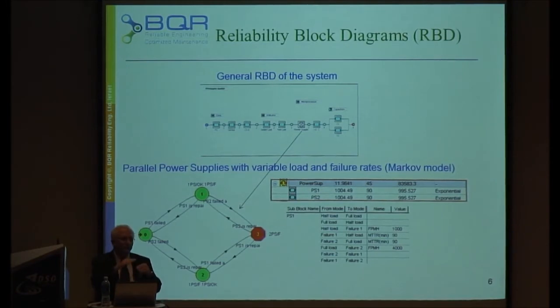And the failure rate starts to increase up to, for example, if we have the 16 balls, if 8 have failed, so we can say that the bearing has failed. So how do we calculate the failure rate of such a bearing in such a situation? Only using a Markov model. So the Markov model is used when the failure rate is not fixed. It changes. It has different states. Every state has its own failure rate, which needs to be predicted based on the condition and the state.